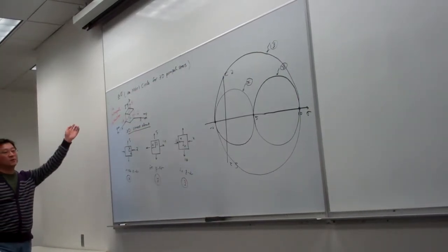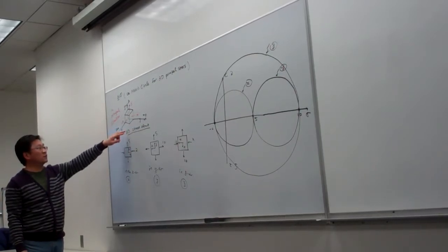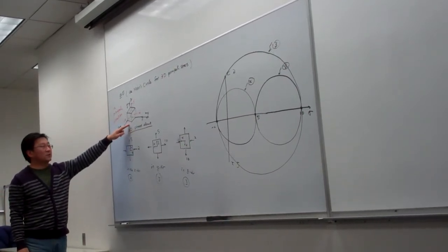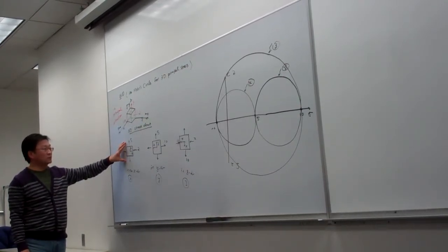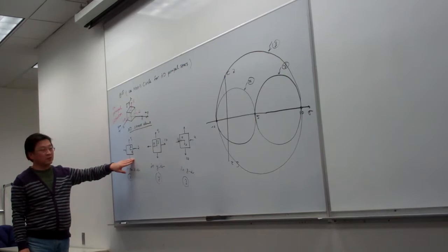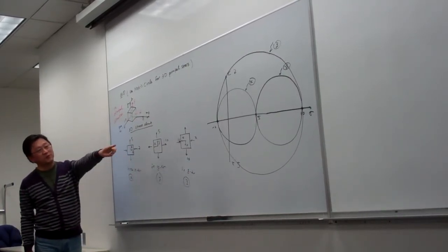So from here, we look into this 3D principal direction, and in front of us is a simple projected two-dimensional distribution of the principal stresses. So for each one, we can easily draw the circles.